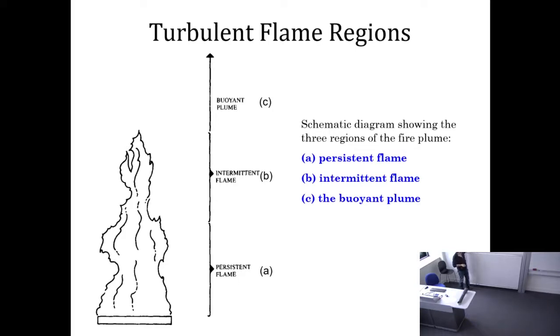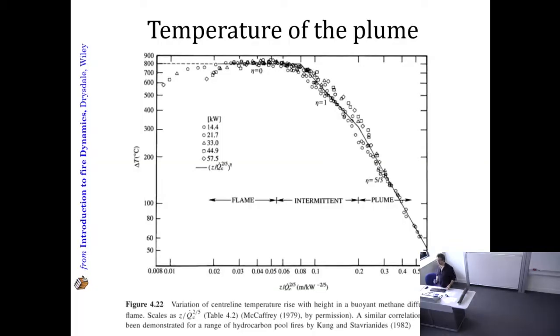It is important because if another fuel finds the flame in the permanent zone, or in the intermittent zone, or in the smoke layer, the ignition source of this fuel will be different. Or if there is a piece of structure, a concrete beam or a timber beam, that is finding the permanent or the intermittent flame or the smoke, it will be challenged by the fire in a completely different way. So this is structure, and the length of the flame is important to understand.